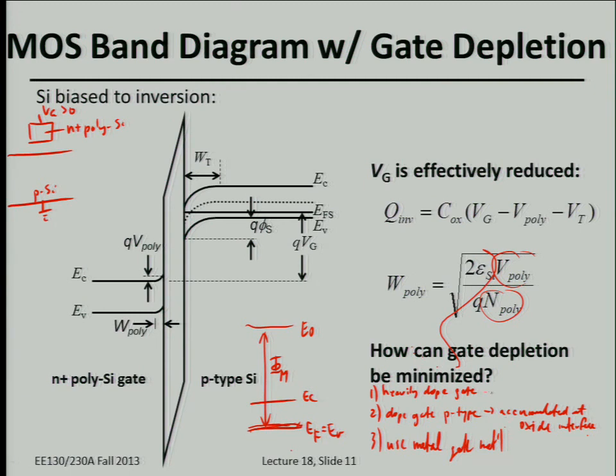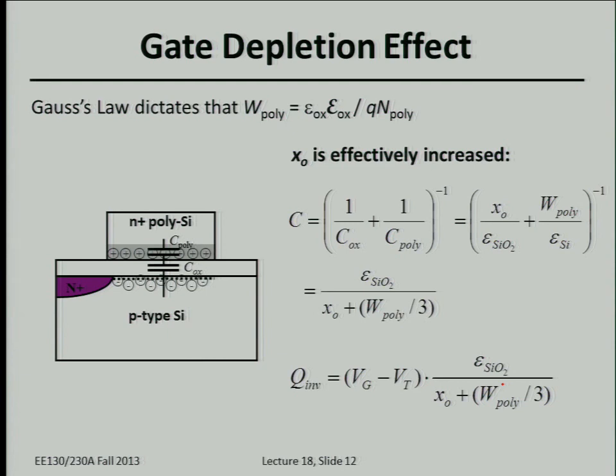In recent years, only in recent years has this metal gate been a viable solution. Before that, many companies developed advanced thermal annealing processing techniques to get as much dopant as possible actively into the gate at the gate oxide interface. The effect, as I mentioned, is to reduce the amount of band bending you can introduce into the silicon when you apply gate voltage.